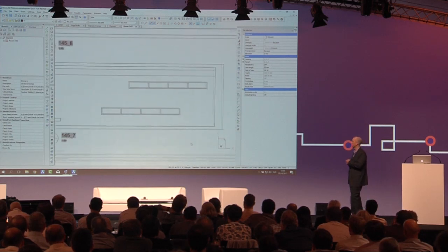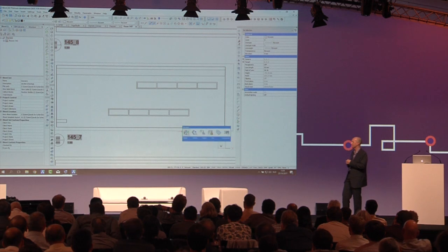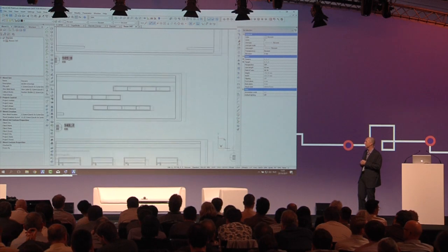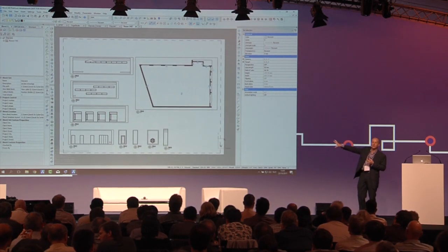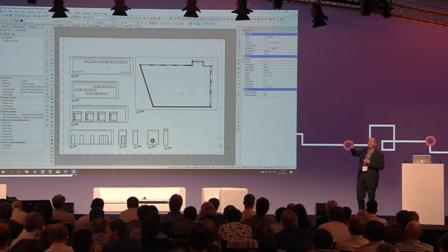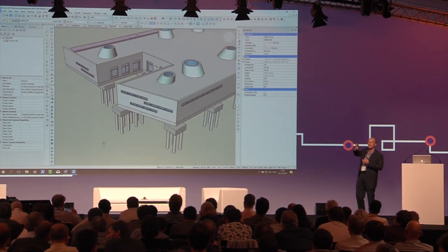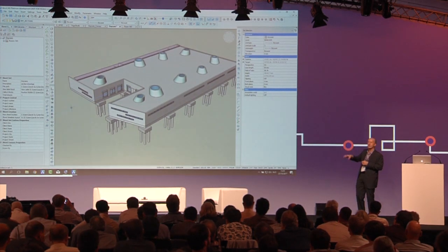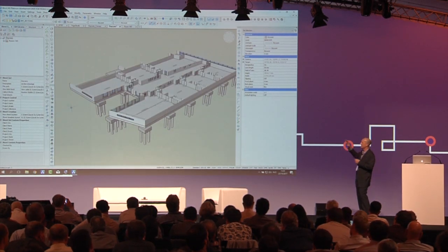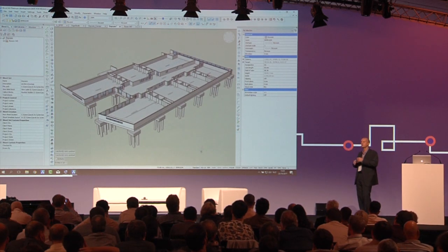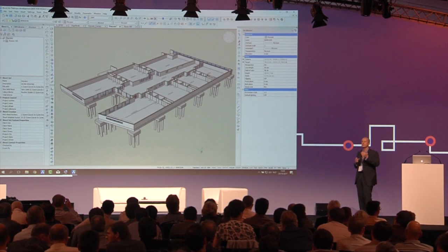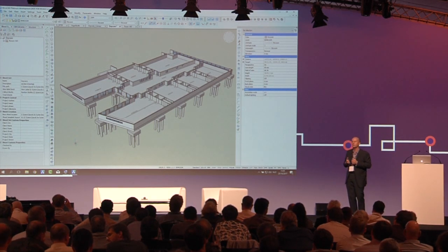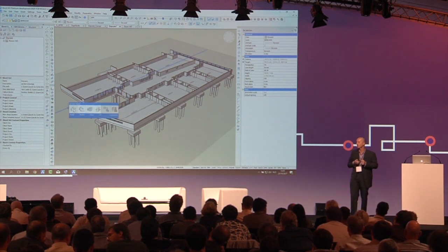And if we go back and look at the exterior wall interior elevation and update that, then we've got our other window appearing. Now, these are obviously simple examples of interior elevations. You can do a lot of other things. You can add details, you can add notes, you can use BIM patch to be able to add further detail to those to get them the way you want. But this is just an example of how we can quickly lay that out so that you can carry your documentation efforts farther faster.